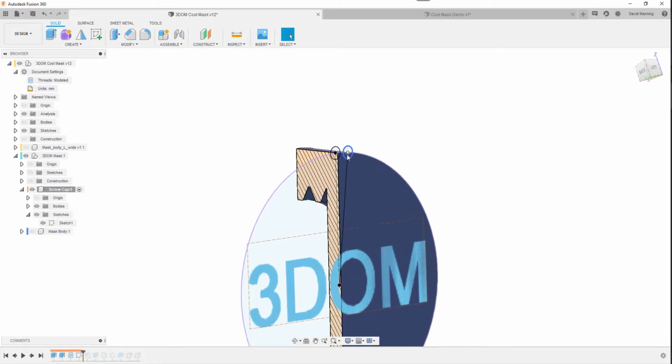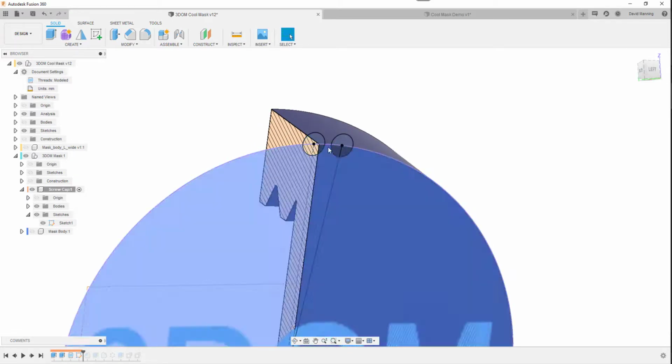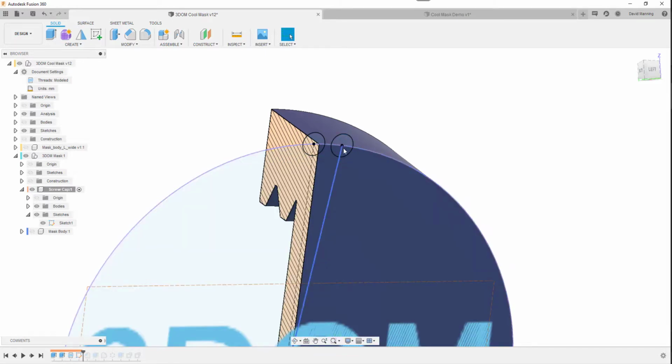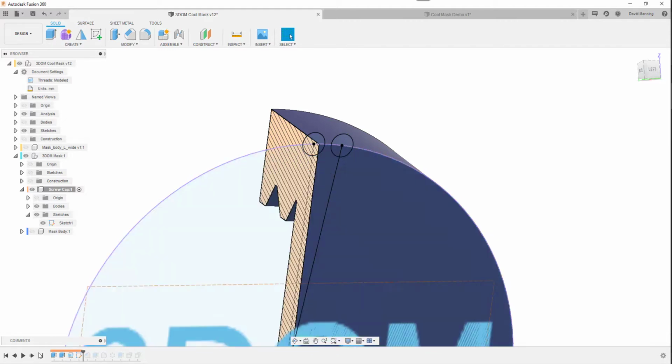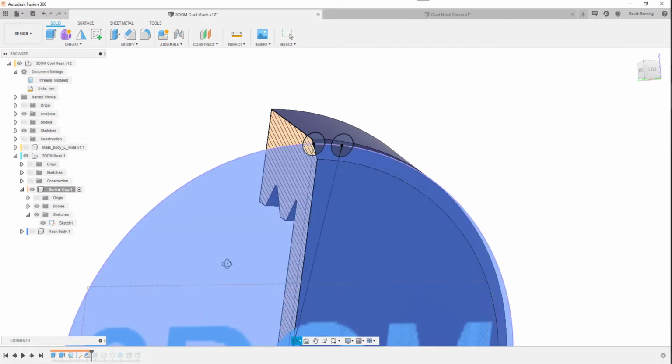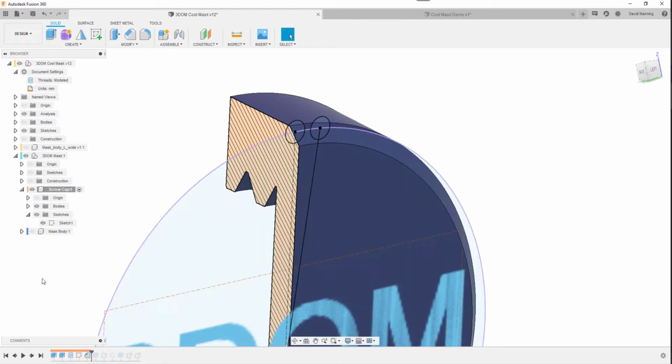The other thing I've got here is I like to put some bit of grippy stuff. So I've got two circles, and I just picked a distance here. The angle there, the two circles are the same size, and the angle is something divisible by 360 to give me a regular spacing. Now I'll show you why I do that, because the next thing I want to do is a chamfer. Now that just makes life a little bit easier to come in the next step. So I'm going to chamfer that edge.